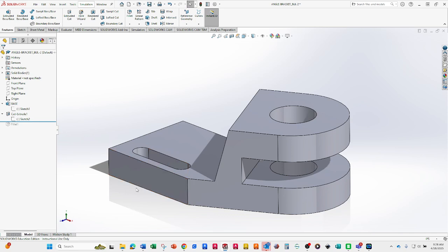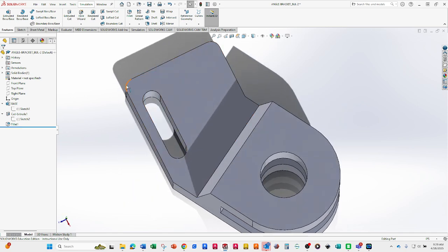Now the only difference is it's actually better for you to put fillets in using the fillet tool. In modeling, it's actually a better practice. For some reason, the modelers like it better. The actual program, the way it works, kind of likes that method better. Now you could have put these arcs, the fillets, in your sketch, and it still would have worked fine, and you would have had 2 steps.